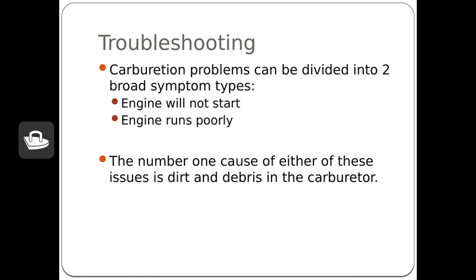An engine that simply won't start, or one that you can get to run, but will do something like die as soon as you try to put it under load, which means like mow your grass, split the wood if it's a log splitter, engage the pressure washer, or turn on your generator. That can be pretty frustrating because then you almost always immediately restart it and it'll idle, but it won't run under load. Many times, again, it's dirt and debris in the carburetor, and we can fix that sometimes by simply taking the bowl off and cleaning it out.